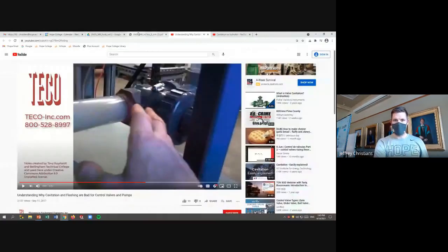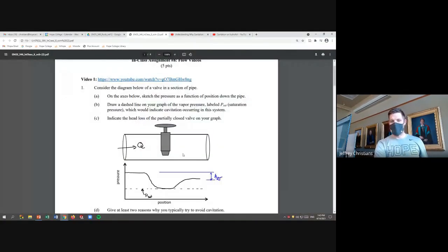I'm going to explain it and not let him explain it. So what's happening, the reason you hear that terrible sound, your pressure is going down, and it's going down so far that you boil and form a vapor bubble, like boiled water vapor. Then when you come back up here, your pressure goes back up.